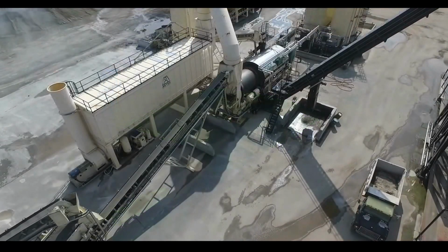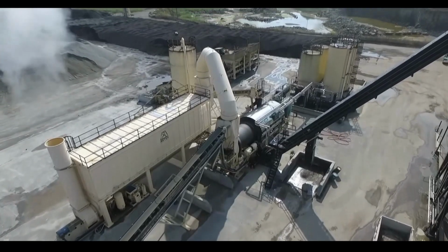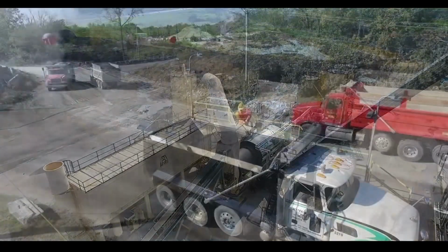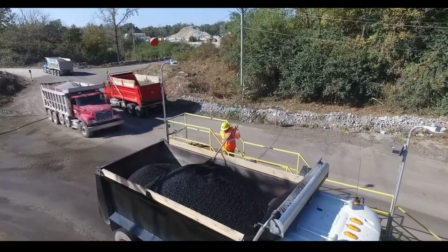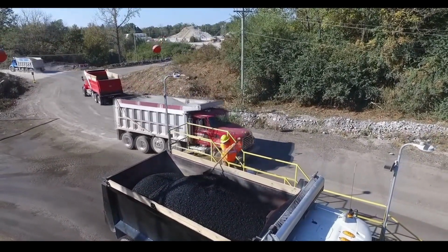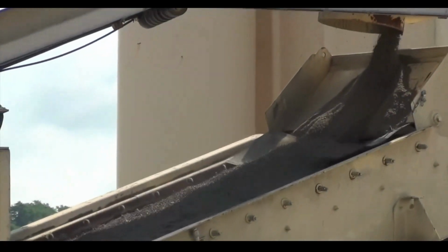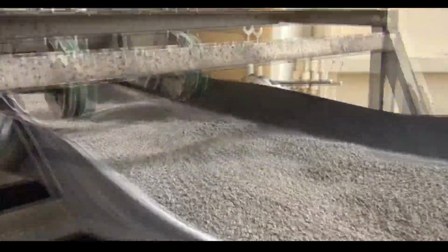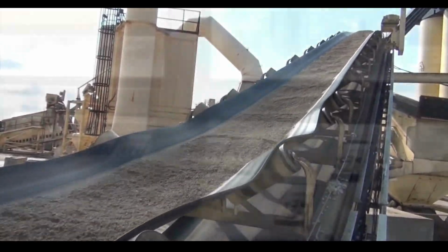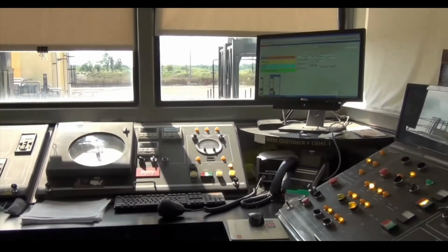With the ingredients checked for quality and a mix design that meets the project specifications, it's time to produce a mix at the asphalt plant. During production, the technician will collect asphalt samples from a loaded dump truck and check the quality of the mixture. It's important to remember that most of the raw materials in the mix are naturally occurring and contain variability. This requires constant monitoring and subsequent adjustments at the asphalt plant where the final mix is produced.